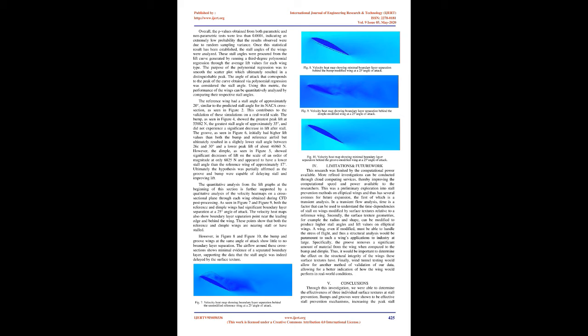This two-factor ANOVA allows us to see how much of the variation in the data can be attributed to changes in individual factors in the data. Based on this, the largest source of variation at 63.8% was changes in the surface texture. 10% of the variation can be attributed to changes in the angle of attack.